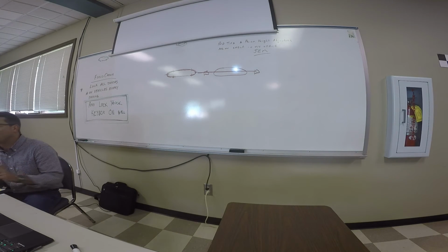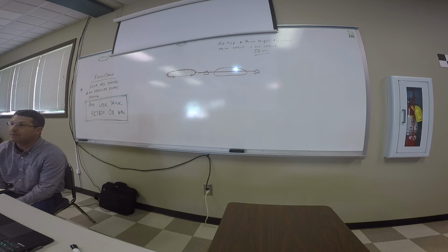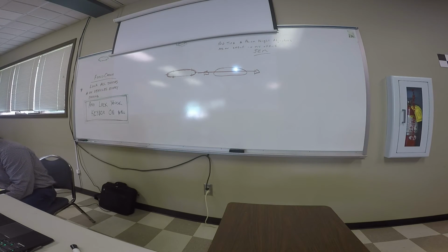It cuts off fire hydrants, because in the past we've always shot fire hydrants up on the top. We've had a previous meeting where we discussed fire hydrants. It doesn't matter. We don't shoot them on the top. We don't use those as benchmarks like we used to. We use our actual control points in the ground. That's what we give people for stakeout, layout, and benchmarks. We're not going to give them a fire hydrant unless we absolutely have to. We want to give them something a little more accurate and that we know was shot very consistently.